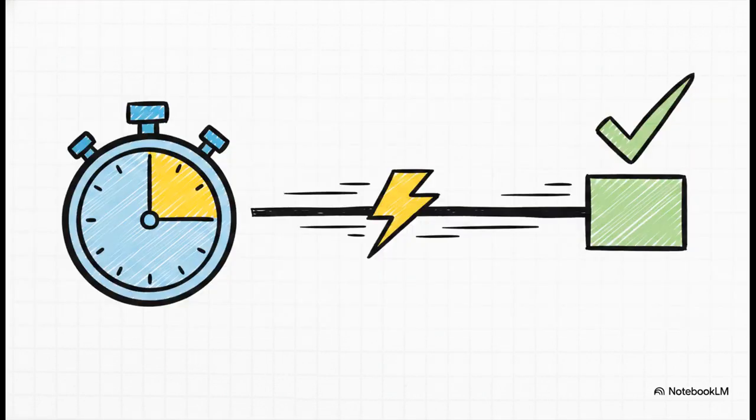Step 10 is timing sign-off. So the crucial point is, our chip might have passed the structural checks, but is it actually fast enough? Using static timing analysis software like Synopsys PrimeTime, we verify the counter works correctly at our target frequency. If we design this counter to run at, say, 500 MHz, STA mathematically proves that the signals can actually travel through those microscopic metal wires fast enough to hit that speed safely without failing.